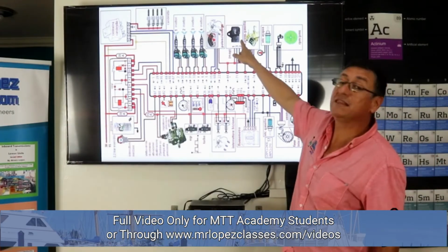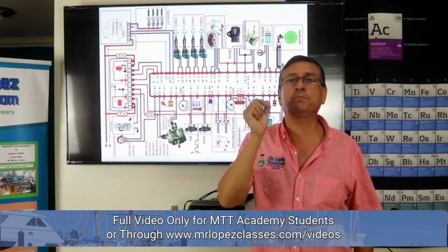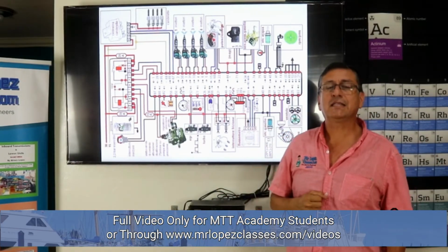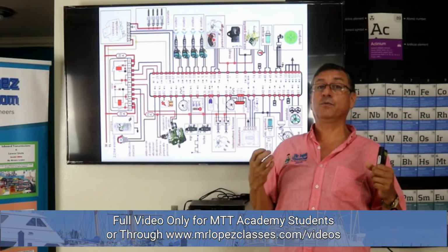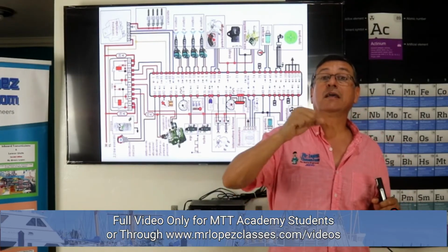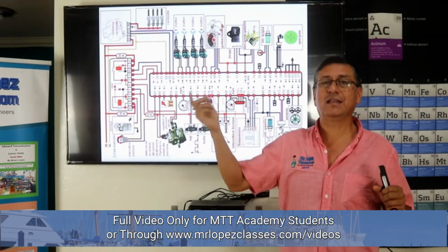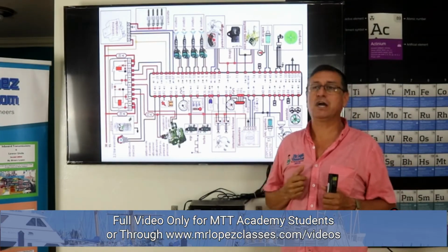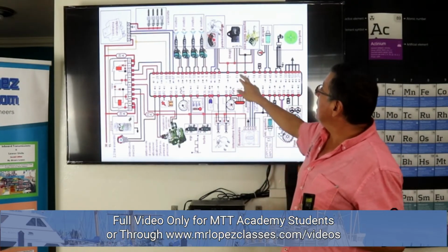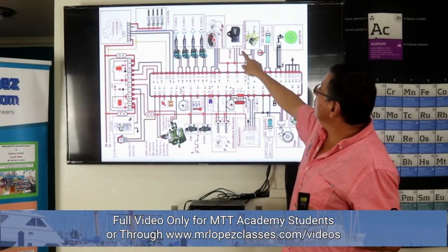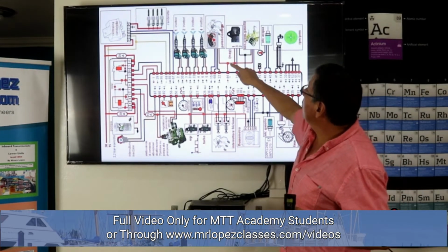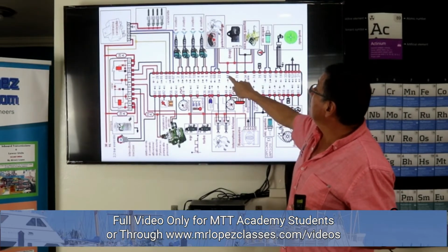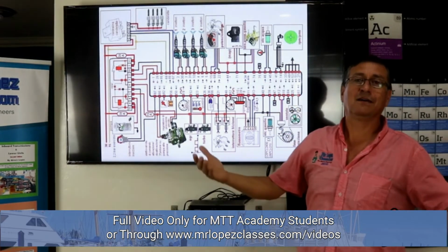Oh, look at the MAP sensor, the manifold absolute pressure sensor. That's critical. That sensor sends a signal to the computer and receives a signal from the computer in order to control RPMs and the wastegate on the turbocharger. In the next episode, I am going to explain the turbocharger. Yes, that's the MAP sensor, and the pins are one pin ground, another pin signal, pin 71, and another pin constant power coming from the computer, 12 volts, from pin 44.